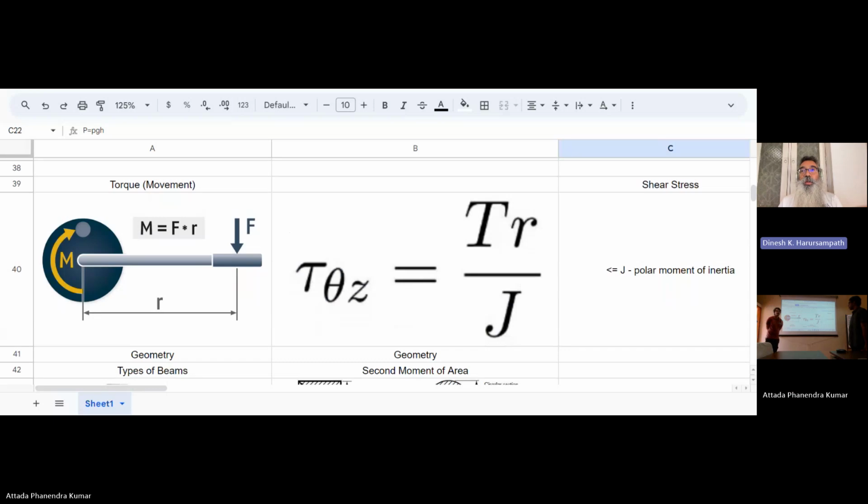So always call it the torsional constant. That is the more general term for it, and it will take on different forms depending upon the type of cross section, because for thin walled, it is very specific. So you can change that polar moment of inertia, whatever you've written there. That's not right.